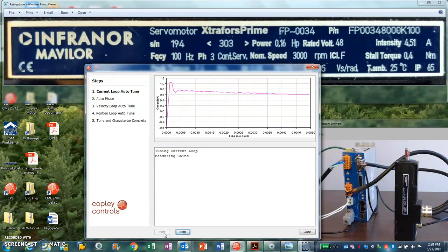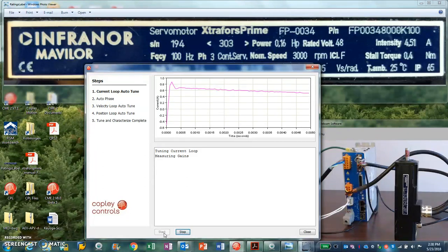Although I like to measure the motor's resistance with an ohm meter, measure the resistance across a pair of wires, and if we don't know the inductance, you just put that same value in for inductance. It's a ballpark figure, but knowing the winding resistance is always good, especially while the motor still works.